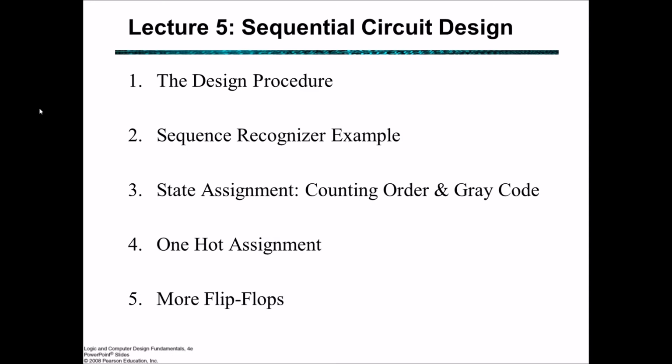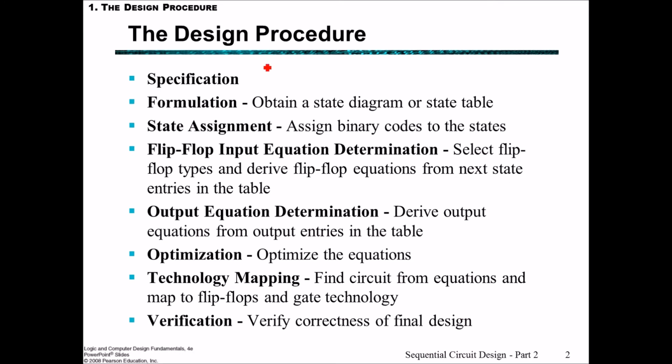So let's get into the design procedure. The design procedure is basically the same as what we had for the combinational circuit design, apart from the addition of these extra steps here. So we still get a specification, we still have to do a formulation. In this case we do state diagrams or a state table.